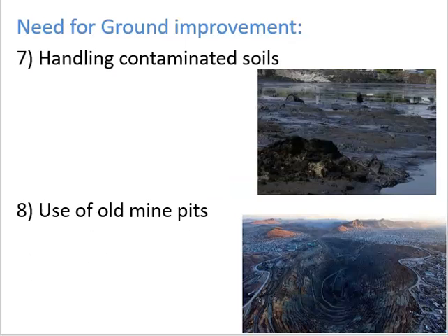Handling contaminated soils. The soils located at landfills, open dumps, mining areas and industries generally are contaminated. The commonly adopted method of waste disposal is by landfilling. If the landfills are not designed properly or if it is an open dump, the leachate generated in the waste will migrate through soil and contaminate the surrounding water sources.